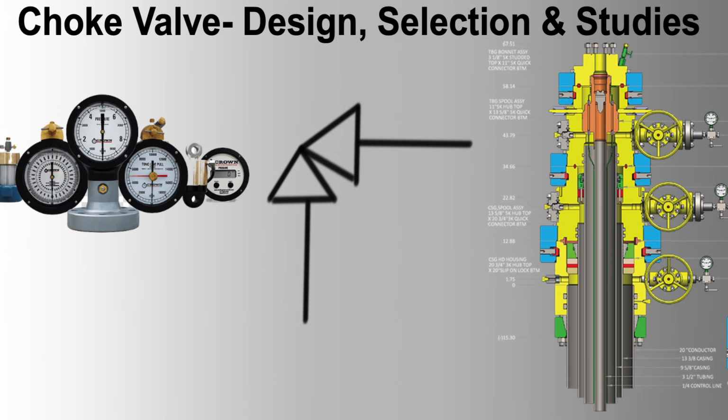2. Control adjustments. Tuning. Regularly tune the control system to ensure optimal performance. Adjust control parameters based on operational data. Response time. Ensure the control system can respond quickly to pressure changes to maintain stability. Maintenance. 1. Regular inspection. Visual checks. Conduct regular visual inspections of the valve and associated components for signs of wear, corrosion, or damage. Performance testing. Periodically test the valve's performance to ensure it operates within specified parameters.